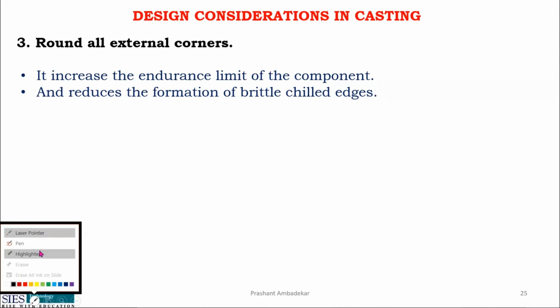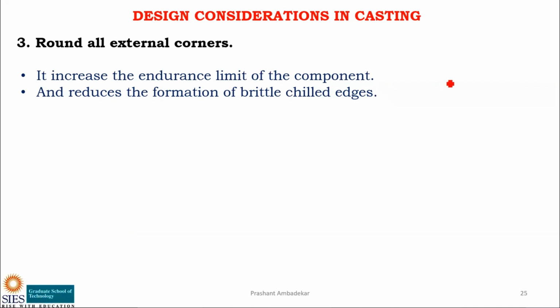Round it up means how can you round it up? Suppose this and this is the part to be designed. So instead of designing it like this, design it in such a way that the corners are rounded. Because of this, what will happen? It increases the endurance limit of the component, and it reduces the formation of brittle chilled edge. So this will be clear in this sketch.